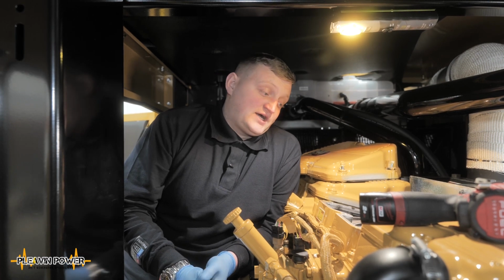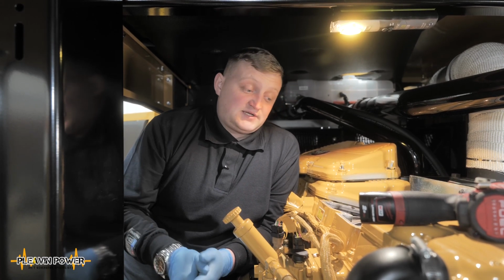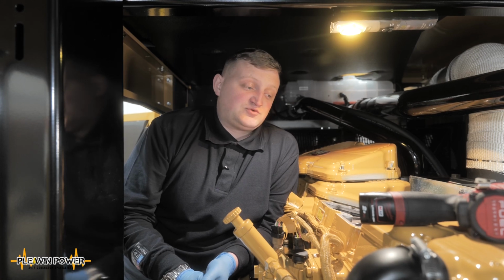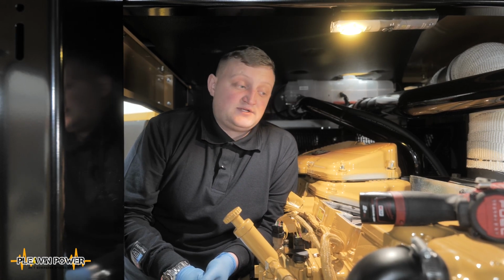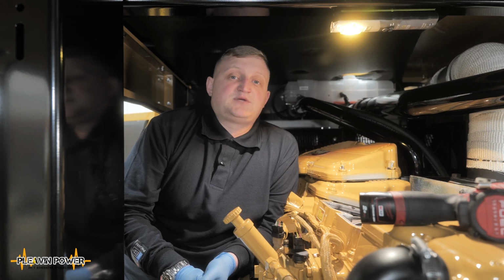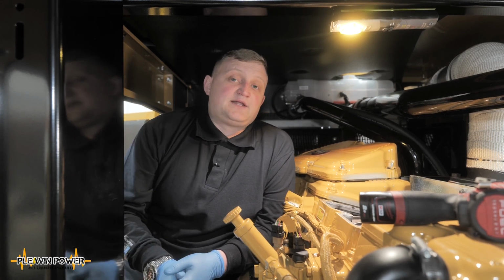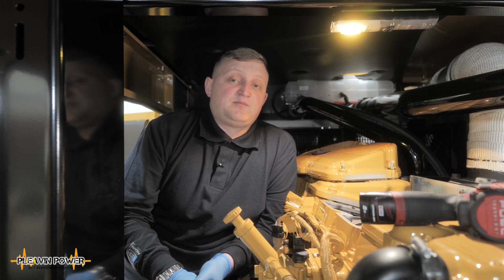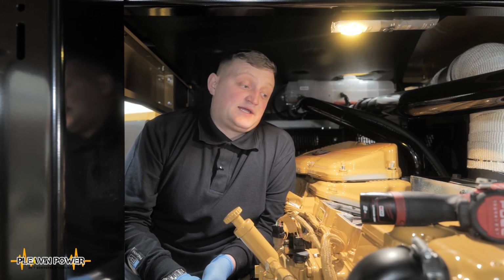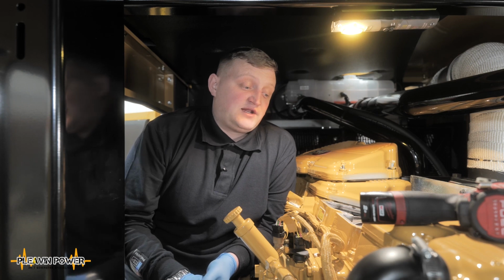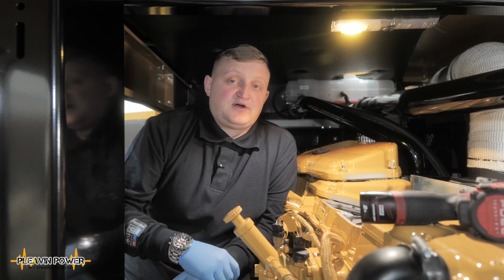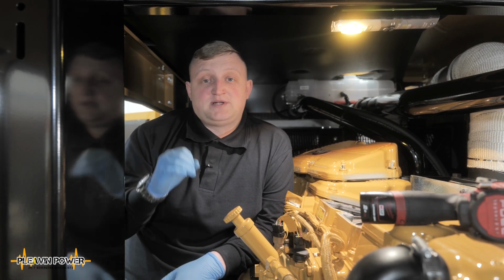Failure to do this can cause catastrophic failure if the valves fail, and as I said before, it can also lead to increased fuel consumption, which can be a good telltale sign that the engine needs the valve and injector adjustments to be completed. If you don't carry this out at the specified intervals, it can leave you with unreliable pieces of equipment, it can lead to hard starting, and it can lead to a catastrophic engine failure should it be used to the point where the valves become so worn that they can fail and drop into the cylinder itself.